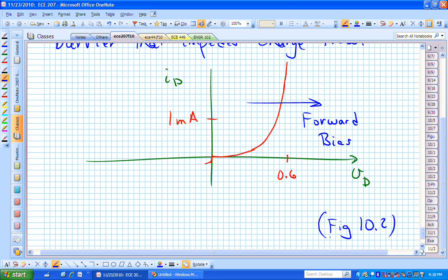Now, if we start biasing this or turning the voltage around across that diode, and I rescale the axis, so the positive side of my current is milliamps in scale, the negative side is now in the nanoamp region. I have very little current flowing when this particular device is reverse biased to a point.